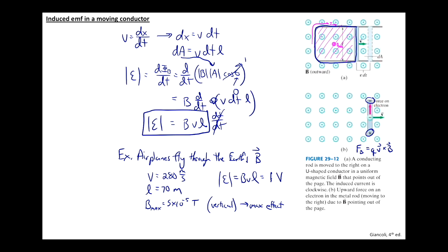It should, but I don't know exactly how. Yeah. Did you say that bottom diagram when we're looking at PVV? Yep. Was that to explain, like, kind of in words why there's an induced voltage? It's two things. It's another way of looking at why there's an induced voltage, but also considering the fact that the equation we ended up with had nothing to do with the remaining part of the loop, the non-moving parts. There's nothing in there related to it, and that explains why.